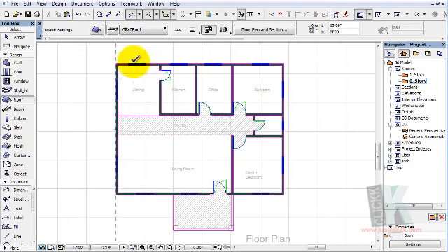You can also give the base height. The base height should be 3450, as the height of the building, and the angle of fall should be 45. Those values are not constant anyway. They vary. It depends on what you want. It depends on your specifications.